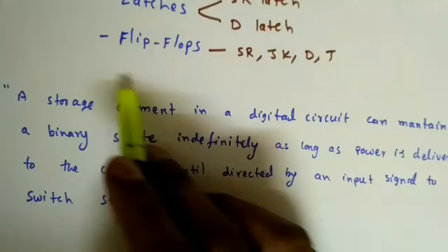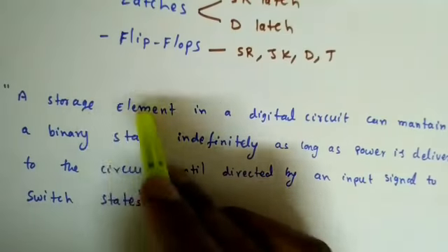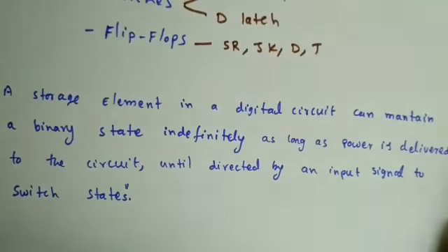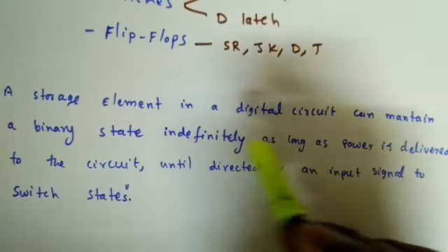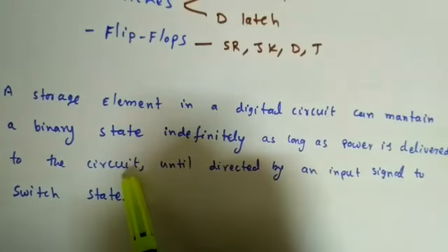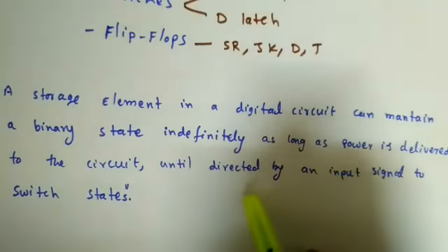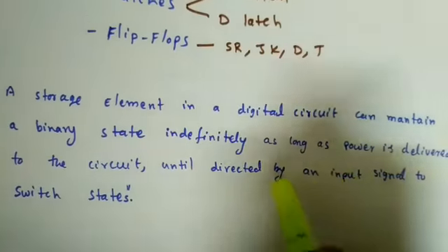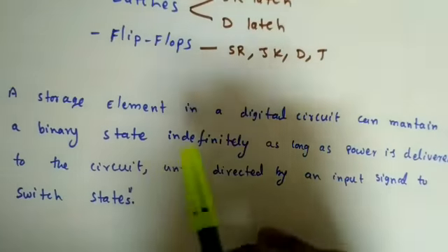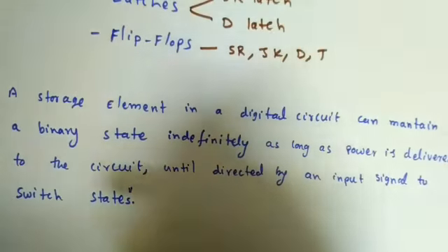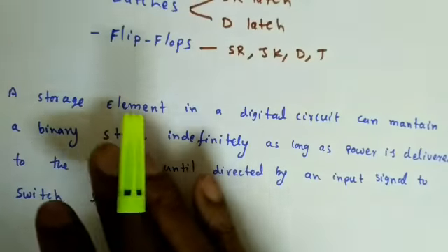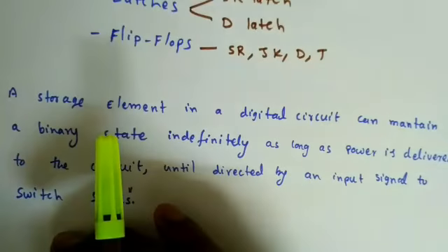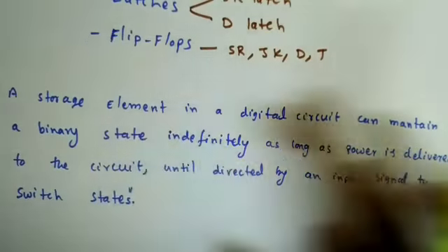Now we will define the storage element. A storage element in a digital circuit can maintain a binary state, that is either 0 or 1, indefinitely, as long as power is delivered to the circuit, until directed by an input signal to switch the state. So unless we give an input to change the state, it will maintain that binary state only, either 0 or 1. That is a storage element.